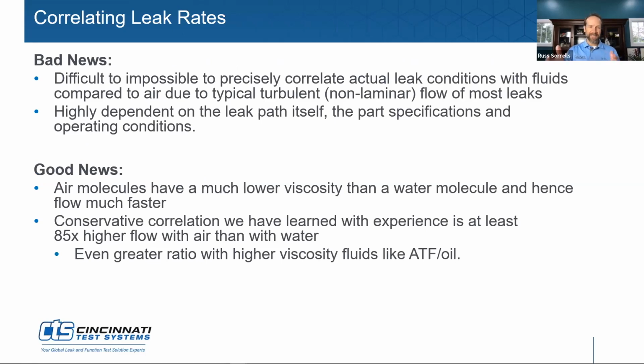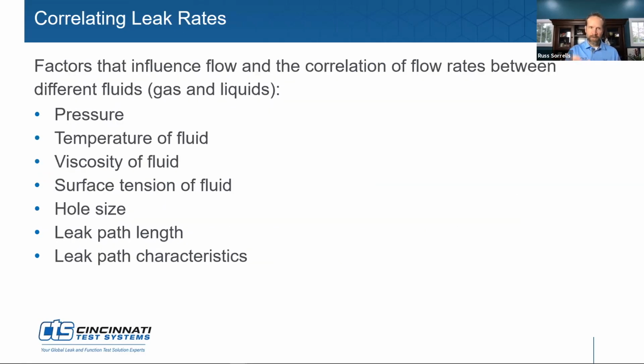So I want to just talk a little bit about correlating leak rates. A lot of our customers want to understand, how does a leak of oil correlate to air? That's what we're speaking about specifically, trying to take a dissimilar fluid and identify what that correlating leak rate would be with the technology that we're going to apply, whether it's pressure decay or mass flow, which is going to be a flow rate of air or gas as opposed to a liquid.